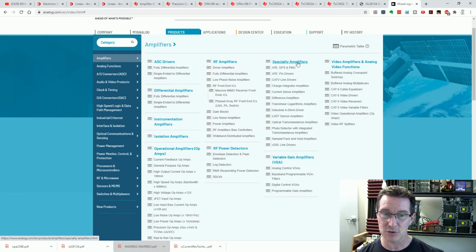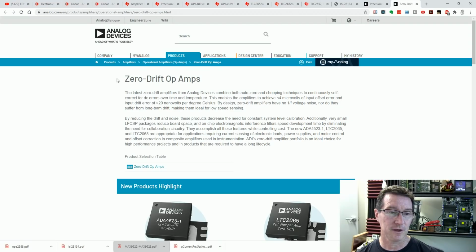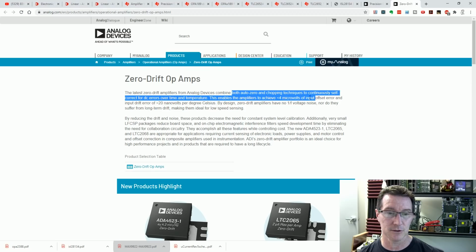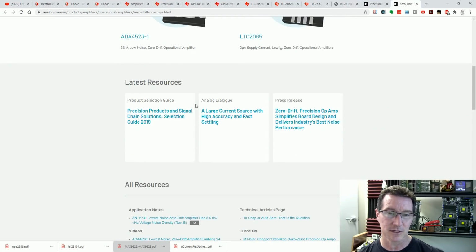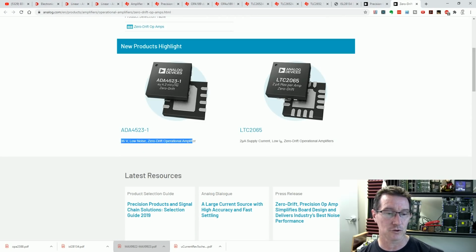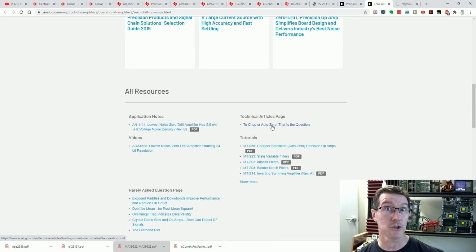Okay, let's go to Analog Devices here. Amplifiers, specialty amplifiers. Precision op amps, VOS less than 1 millivolt. Yep, that's what we're... Zero drift. No, we don't want a zero drifter. Zero drift, there we go. Zero drift op amps combine auto zero and chopping techniques to continually correct offset, less than 4 microvolts. So it looks like Analog Devices, and 2 microamps. Oh, they've got a 36 volt jobby too. Whoa. To chop or zero? That is the question.